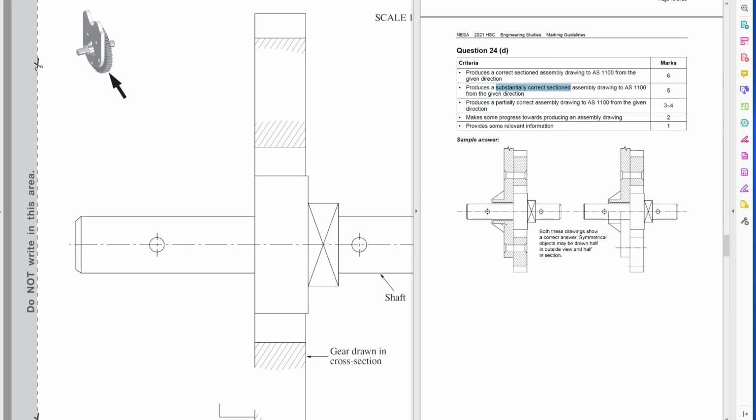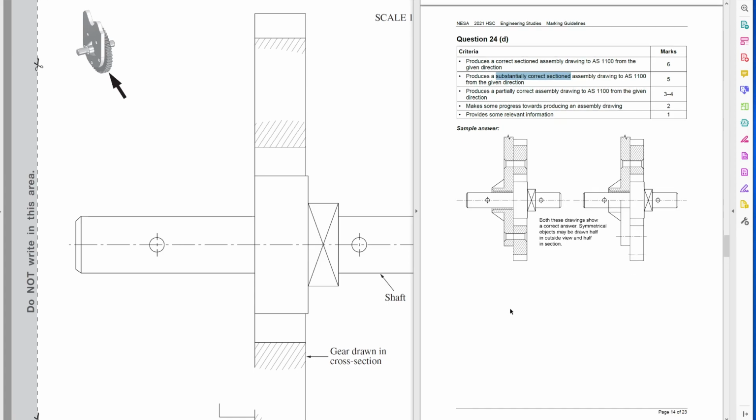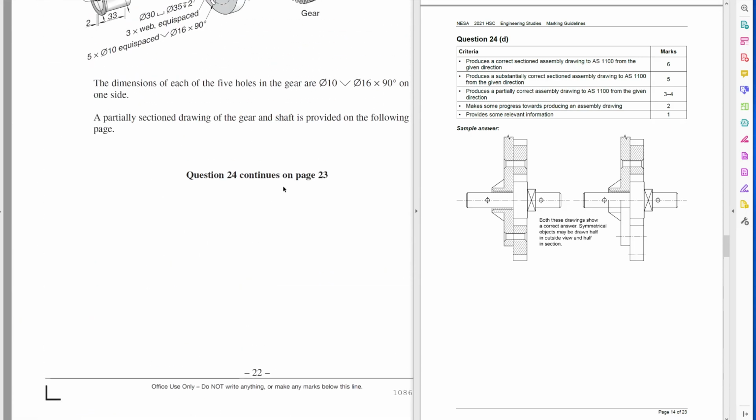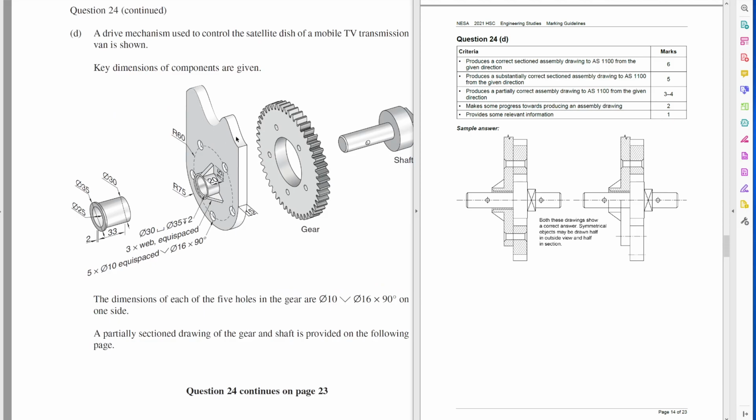What are things that people get wrong? They might not draw this as being PCD, and they might not draw this as being PCD. They might forget to show the countersink. So that's a mistake. That's a mistake. Not showing the right sectioning here is a mistake. So that's 3. 4 is getting this wrong. 5 is just the general shape. 5 and 6, I would say that if you just draw the general shape, you're going to get something. Oh, the break line. The break line would be another thing. Yeah, because this shape continues into the page, right? This isn't the end of the shape. They just can't show the whole thing. So that's the break line.